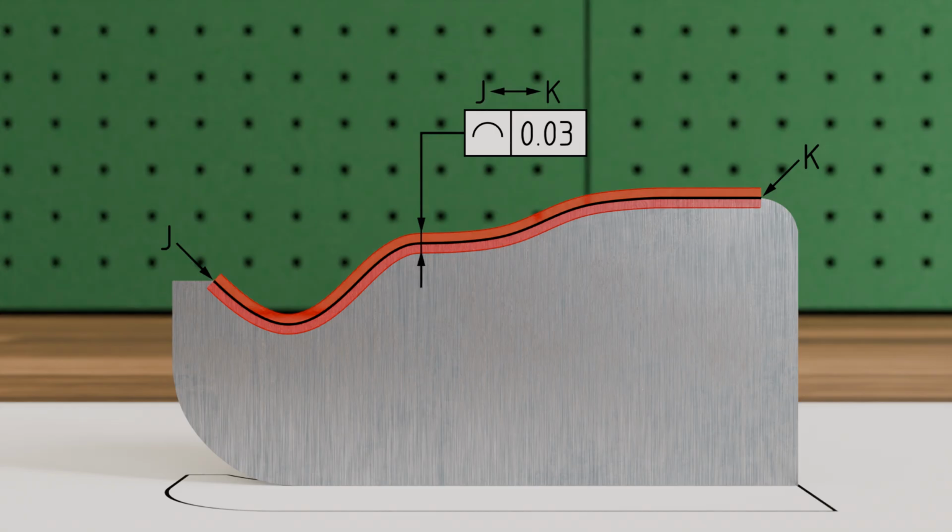However, the ends of the tolerance zone are not rounded but oriented perpendicular to the line profile. The actual geometry of the sheet metal edge must lie within the resulting tolerance zone. However, the tolerance zone itself does not have to be exactly aligned with the ideal geometry. It can be positioned arbitrarily relative to it.